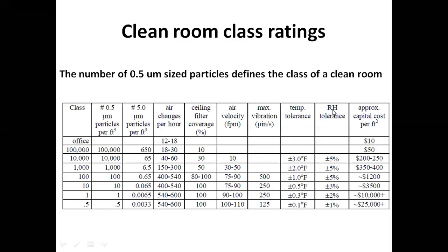Relative humidity is also very important. Normally we keep around 60% humidity inside the clean room. This is the relative humidity tolerance. So plus minus 1 for 0.5 class rating and 2% for 1 class rating and so on.